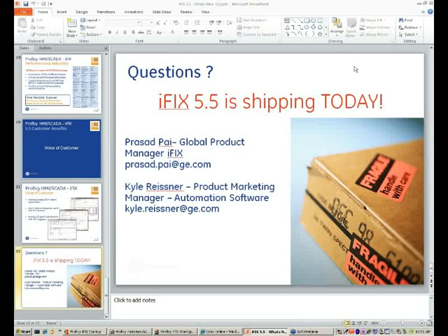In iFIX 5X and ideally iFIX 5.5, since you would upgrade to iFIX 5.5, has a more traditional active standby concept on the SCADA. So I think that is something that you will have to watch out for. Depending on how your application is structured, it's quite possible you may not have to do any changes there. But I know customers who had written specific scripts around the way 4.5 failover worked, and you'll have to watch out for that behavior of the SCADAs.